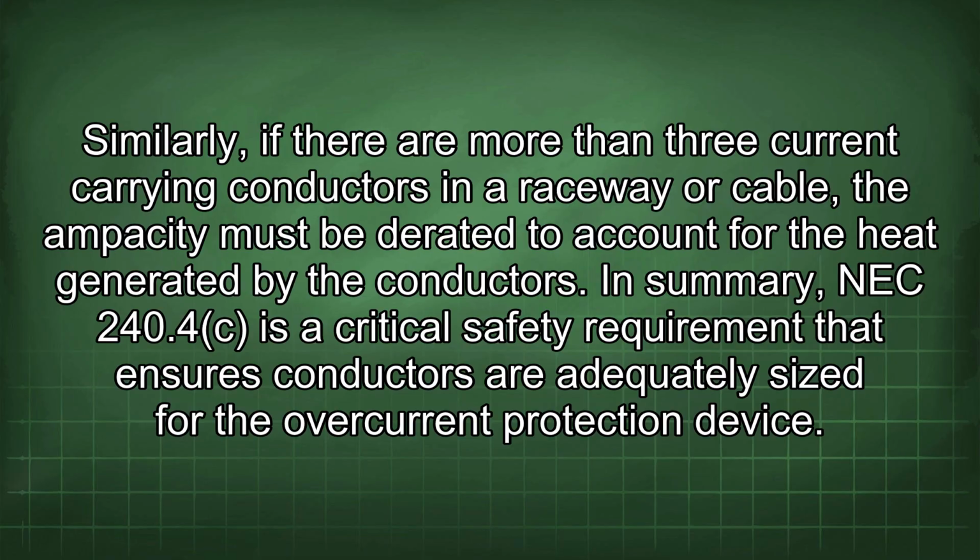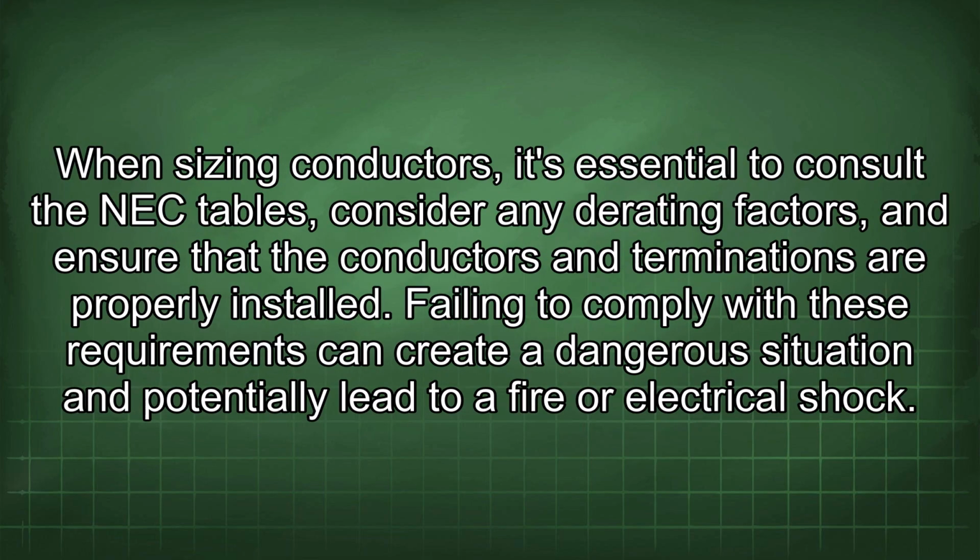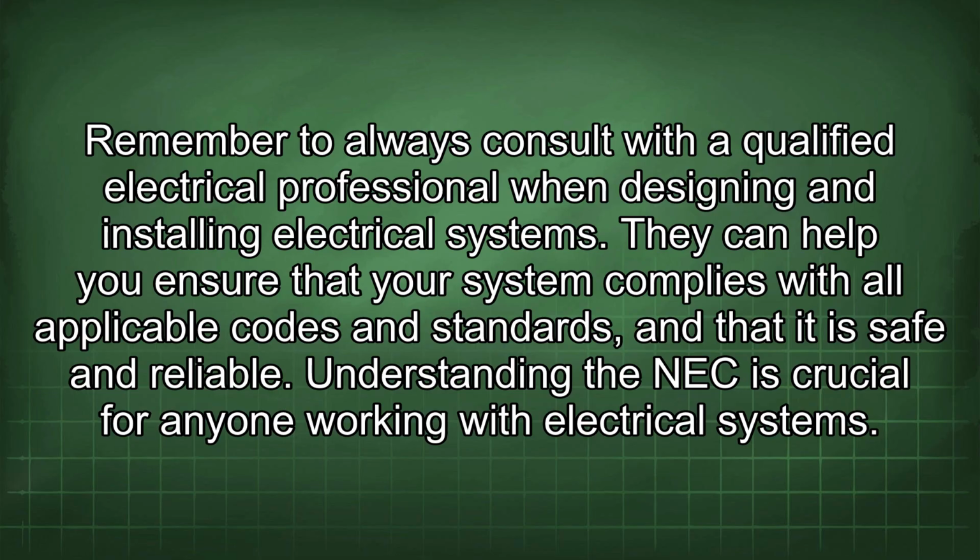In summary, NEC 240.4 is a critical safety requirement that ensures conductors are adequately sized for the overcurrent protection device. When sizing conductors, it's essential to consult the NEC tables, consider any derating factors, and ensure that the conductors and terminations are properly installed. Failing to comply with these requirements can create a dangerous situation and potentially lead to a fire or electrical shock. Remember to always consult with a qualified electrical professional when designing and installing electrical systems.